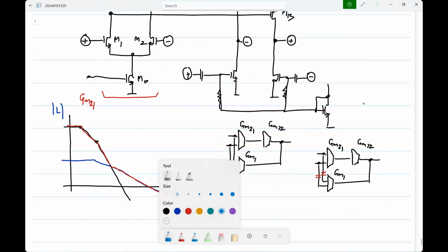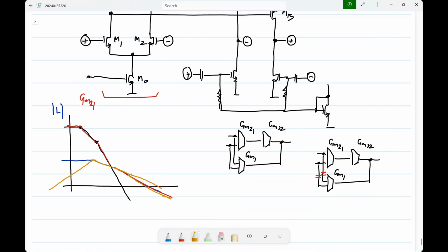So basically, low frequency of which one? So it's not that. This part here doesn't change because that is still DC coupled. Okay. So this part, instead of doing that, it could have done something of this sort, right? It could do that. Okay. But even if it does that, the sum remains almost the same. So it doesn't really matter. So AC coupling could potentially be used here.